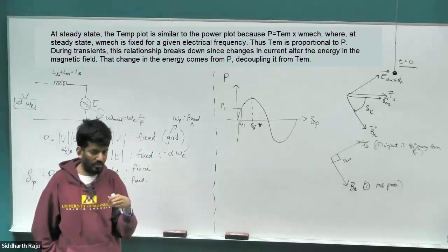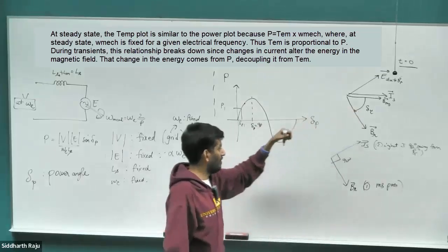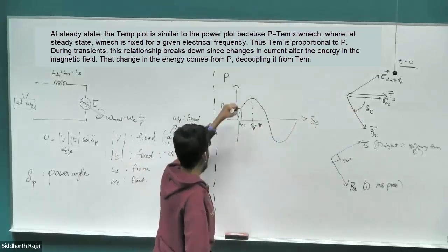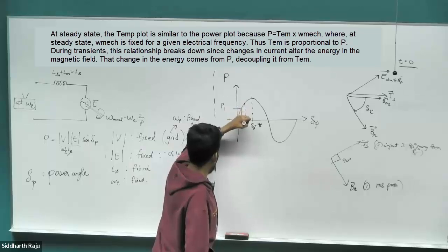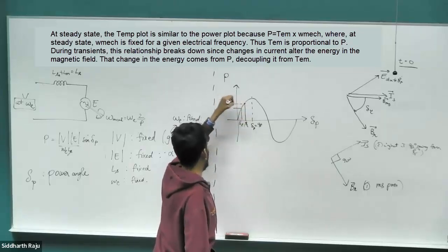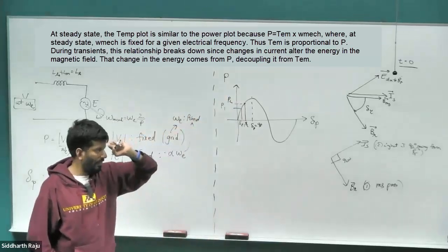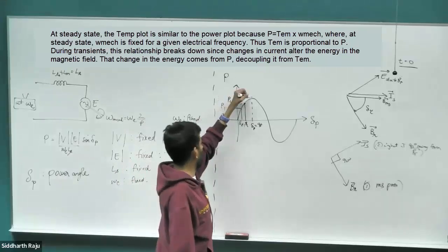That means the angle between the rotor angle and the stator starts to lag behind. Delta increases. The same logic comes here. Delta would increase, and you would go to a new position, delta P2, where you would generate higher power. If this power now satisfies the load demand, this would be your new stable operating point. And this can keep on happening until you reach this point.